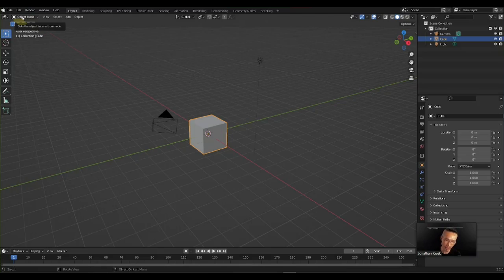But if you want to dive in one level deeper to change something about that object that you selected, then you have to go into the edit mode. That's very important. And when you're done editing that object, you want to go touch another object, then you have to exit that edit mode and go back to the object mode. Got it? So object mode, dive deep into edit mode, then dive out again to do other stuff.